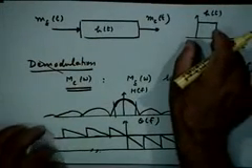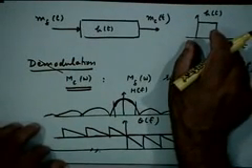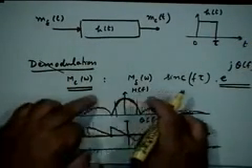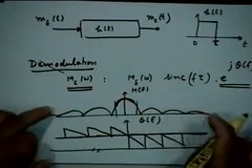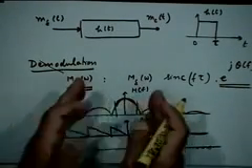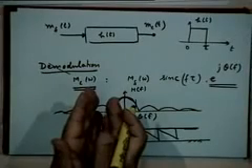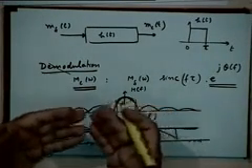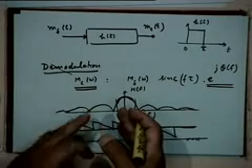Mind you, this really will become unnecessary if your pulse width is very small. Suppose this pulse width is really very small, then this main lobe will have a very large width, and it will be more or less flat in the bandwidth of the message signal. So in that case it will not be necessary, and intuitively that makes sense, because if the pulse width is very small, you are back to more or less impulse sampling. If the pulse width is large, then equalization becomes important.